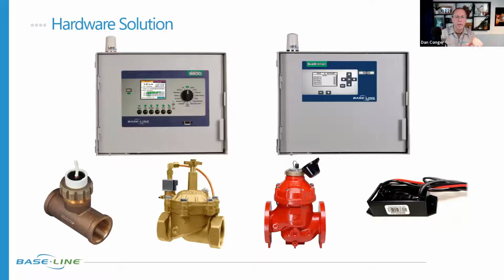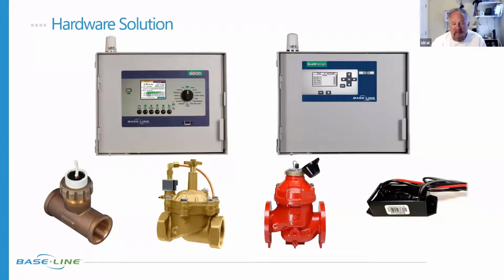And then they used 4 of these event switches, or event bicoders. Fill me in on how those came into play and what they used them for. Okay, so there's a sensor in the cistern that is set up through Watertronics. They utilize the signal for different things that the pump needs to do, but we also utilize it. It's measuring in inches the amount of water in the cistern. We should have mentioned earlier, we can't actually use the full 64,000 gallons. We can only use everything above 35 inches. Below that is below the suction line. So it's even less water than you think, but the capacity is 64,000.